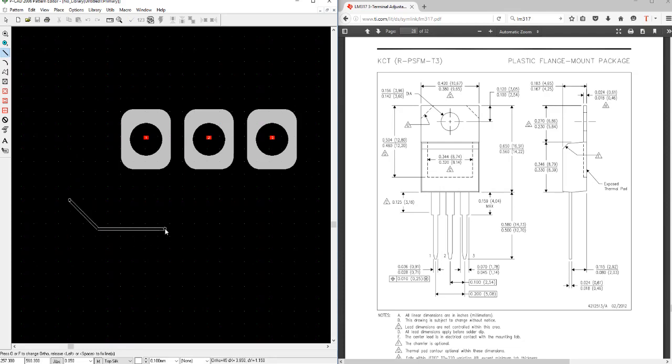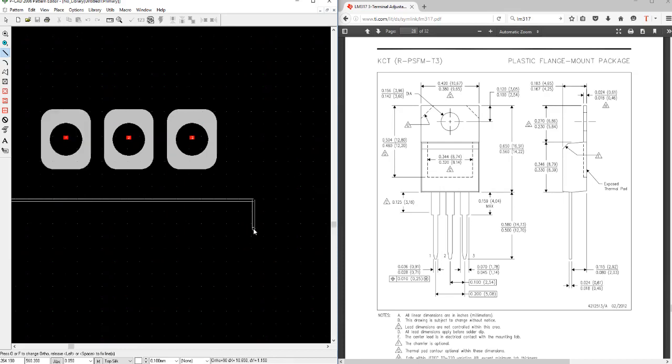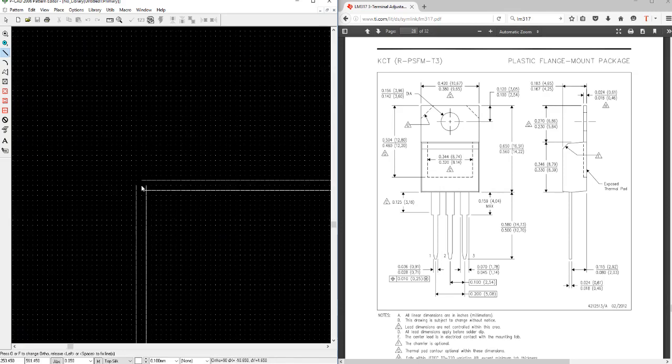and if you draw your line and you see this, you can press O again. Here we keep watching at the bottom the dx, and we get that to 10.67 millimeters, 10.65. There we go, there's 10.65. Then I just click and let go. Then I press backspace to take this horrible little segment away. Then I click again, and now I do the bottom side going to 4.65, like that. Backspace again, click again, zoom in, zoom out with plus and minus.